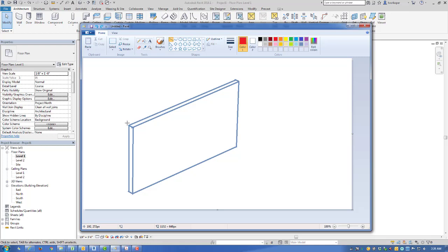And then Revit will want the other layers. So we have a stud layer here for a wall, and then we will come in and draw a chipboard layer. And we'll define the wall this way, and so we don't have to draw all these layers as we work our way through Revit. We just say, for this wall type, we want chipboard on the inside, like so. And now whenever we model this wall type in Revit, it'll come with a stud layer and a chipboard layer.